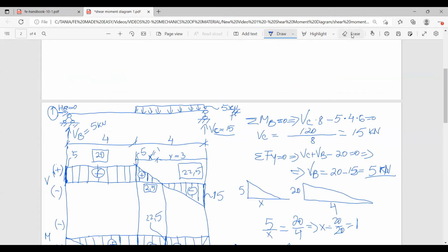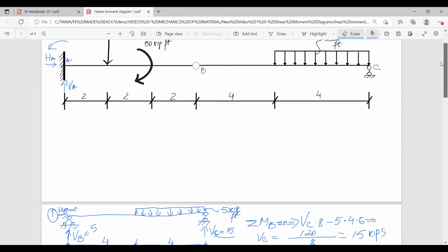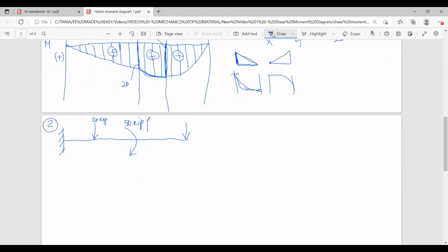No, I just realized that this is actually not kilonewtons per feet, it's kip per feet, because it doesn't make any sense, correct? Like, what have I done here? So this is actually kips, and this is actually kips, and kips. I will go ahead and just take it away from here. I hope it didn't confuse you, and if you caught that, good for you. Okay, so I have a 20, a 50 kip load moment, kip foot, and this is 5 kips.